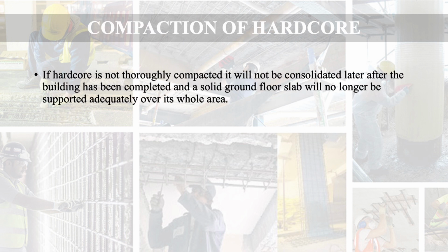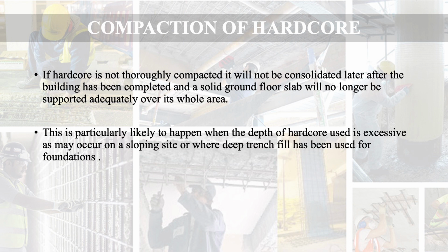Then compaction of hardcore. How does it affect? If hardcore is not thoroughly compacted, it will consolidate later after the building has been completed, and a solid ground floor slab will no longer be supported adequately over its whole area. This is particularly likely to happen when the depth of hardcore used is excessive, as may occur on a sloping site or where deep trench fill has been used for foundations.